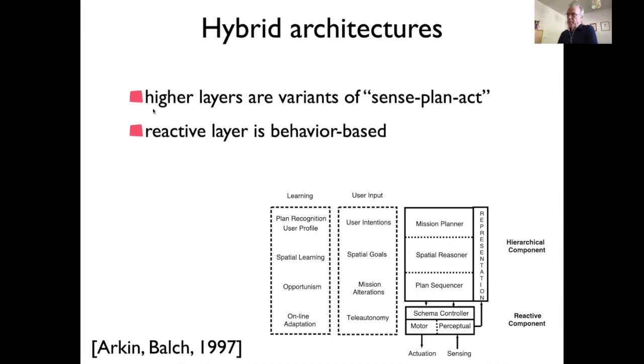And that's very common. It's sometimes called a hybrid architecture because it combines these so-called subsymbolic and the sense, plan, act kinds of approaches. And that's the state of the art today. You will have many systems like that. And a lot of the autonomous driving algorithms actually have some kind of architecture like that, a low reactive planner, and then planners with longer and longer planning horizon, and that make more demands on sensory information and mapping.